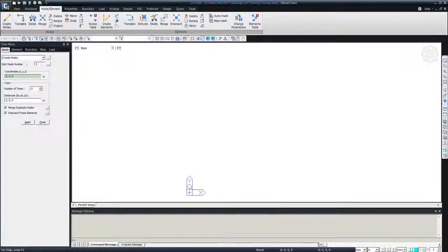All right, so I start creating them. Let me put this on the feet for now because the main geometry I'm going to create is based on the feet, and then when you go to create the sections, I have the data for the inches. All right, so the first node will be 0, 0. Just click apply. It's going to be in the point of origin.